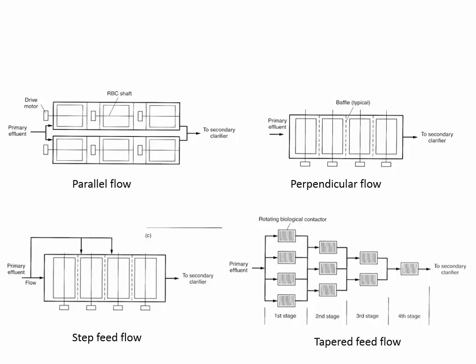It's a little bit counterintuitive, but what we're trying to do is make this one plug flow reactor, this another plug flow reactor, and this a third plug flow reactor, and each of them will start off at the first part of it having a high concentration. So you're trying to get more of the reactor into the mode where you're having a high rate of removal.